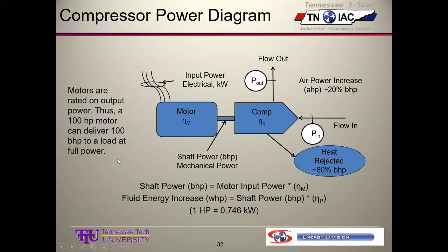Now, what we see air compressor manufacturers doing is putting motors on things that have a service factor of 15% typically, and they will design the full load power requirement of the compressor into the service factor, which means they might have that compressor pulling 105 to 110 horsepower on a 100 horsepower air compressor that has a 100 horsepower motor. Now, so long as you keep this motor cool enough and you don't exceed the rated service factor on the motor, you're probably going to be okay.